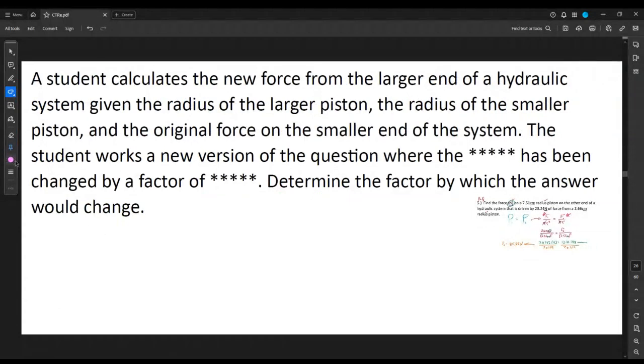Okay, then part of the reason that we learned about pressures, and in particular fluid pressures, is so that we can set up and see systems. So the hydraulic system changes the size of a piston from one side to another and can use that to increase force considerably. Occasionally the pistons are the same size on either end, and basically it's just to transmit force through the means of fluid pressure, but we're going to look specifically where there's a small piston and a large piston.